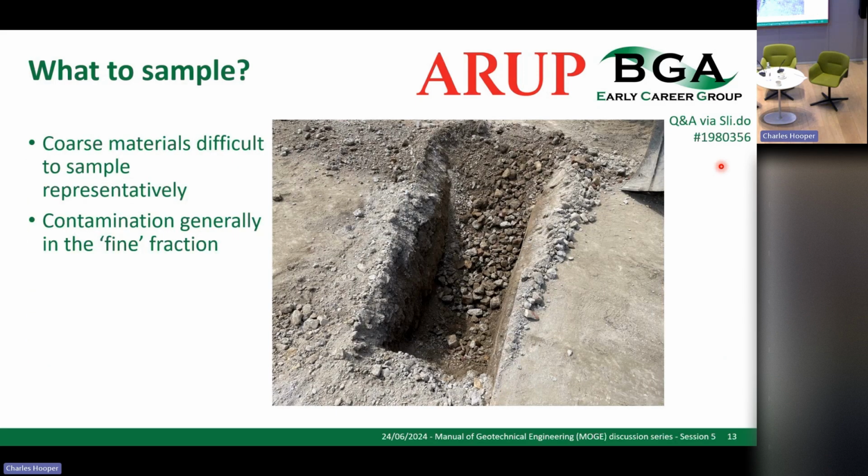The other thing to look at is gravels, basically. Coarse fractions are very hard to sample for geo-environmental works. For a geotechnical test, you'd want to take a very nice representative bulk of it with all those size ranges present and accounted for, and you may have to take several bulk bags for it. For the environmental aspect, primarily your contamination is going to be focused within your fine fraction. Those lumps of concrete and brick are unlikely to really represent a risk when we're looking at, say, our inhalation, ingestion, dermal exposure. They're just not the main source. If we had something like a clinkery material, we may have to change that approach, but your usual rule of thumb is that they're not really going to be representative or required for contamination assessment.